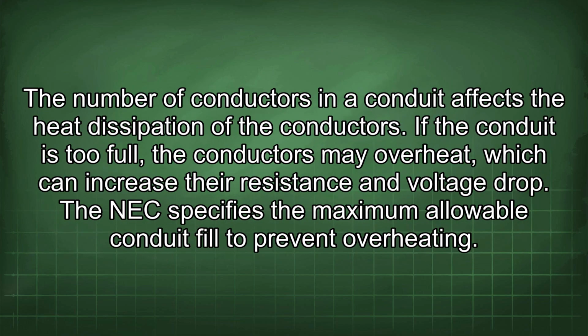13thly, conduit fill. The number of conductors in a conduit affects the heat dissipation of the conductors. If the conduit is too full, the conductors may overheat, which can increase their resistance and voltage drop. The NEC specifies the maximum allowable conduit fill to prevent overheating.